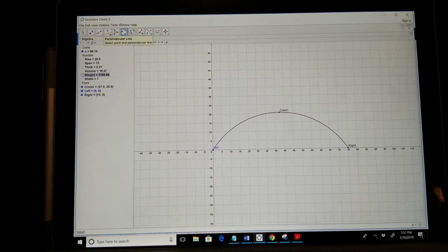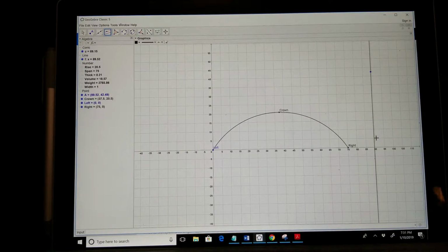So we're going to create the force diagram by doing parallel lines, drop it over here, and I'm not going to draw 8 little circles. I'm going to draw one big circle. The radius will be the weight of the course divided by the force scale because that's thousands of pounds and I want it to fit on this page.